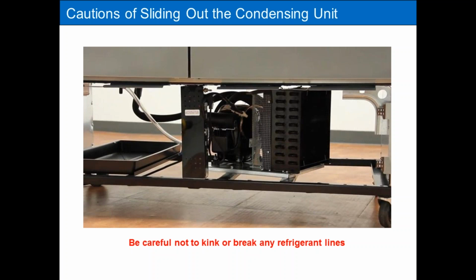It has happened to me, I hate to admit it, more than once, several times in my lifetime, and it's never a good scenario. One time I was working on a cooler, had it all fixed. I changed the compressor out and everything was perfect. I had the unit outside of its cavity. It ran like a champ, and as I was pushing it back in, I just kinked the suction line and caused it to crack, and all the refrigerant dumped out.